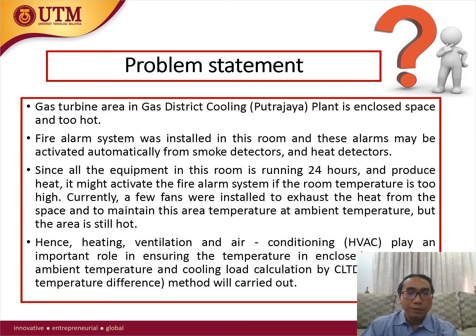Currently, a few fans were installed to exhaust the heat from the space and to maintain this area's temperature at ambient temperature, but the area is still hot. Hence, heating, ventilation, and air conditioning (HVAC) play an important role in ensuring the temperature in an enclosed space is at ambient temperature, and cooling load calculation by the CLTD, cooling load temperature difference, method will be carried out.